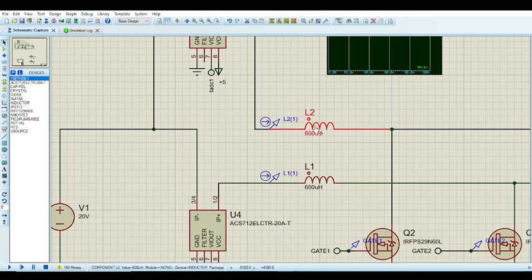So you want the size of the inductor to be high enough such that it stays continuous at a particular switching frequency. And obviously, if you don't want this to be too high, then you're gonna have to increase the switching frequency. On this particular microcontroller, that's quite difficult to do, because as you increase the switching frequency, the resolution just dips. So you want to do that on a different microcontroller, not a more advanced architecture, just one more specific for the application, tailored for that. ST, TI, STM, etc.